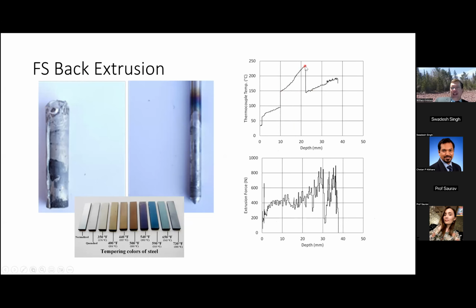And so now we're measuring within the recrystallization temperature, and we've actually gotten to test up to 450 degrees Fahrenheit. So well within the recrystallization temperature. And we then started looking at the probes and the discoloration, which we could relate to the tempering colors of steel. And we found that we were getting up within our visible region somewhere around 310 Celsius. And actually, if you look down here, we are even in this region. So we were getting up to maybe even 388 degrees.